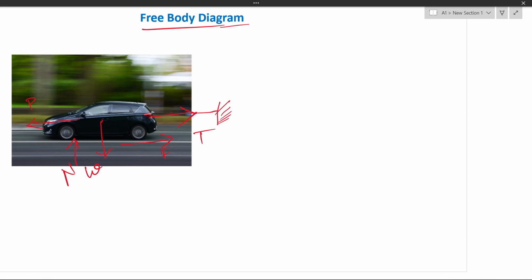To draw a free body diagram of this object, we show the tension and the external load. If P is greater than the tension, the object will move in this direction, so friction will also be in this direction, along with the self weight and a normal force.